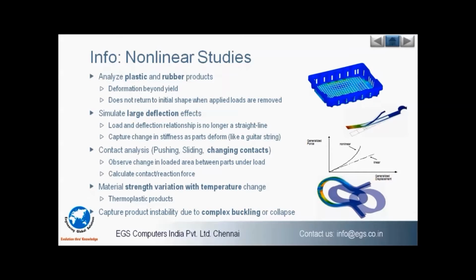Coming to the information on the nonlinear studies, we are going to analyze the plastic parts and the rubber products. If our organization is dealing with plastic components or rubber components, nonlinear analysis is very helpful to study the deformation beyond the yield value. As we have all studied in the mechanical industries, at the stress point, when the loads are applied, the product is not going to retain its original shape. That means the material has undergone a plastic deformation.